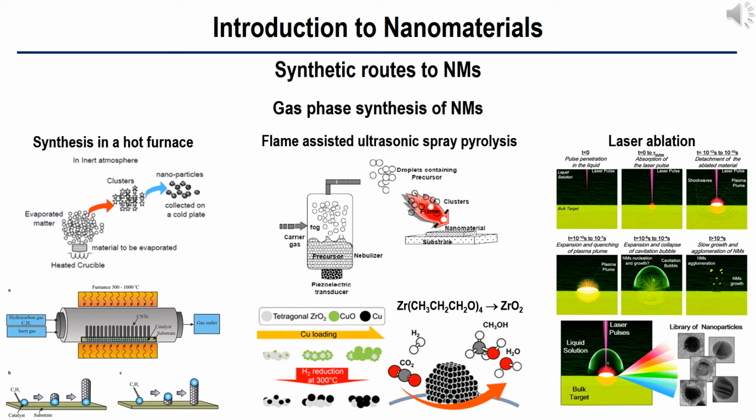In case a compound is being synthesized, these precursors react in the gas phase and form a compound with the material that is separately injected in the reaction chamber. The clusters would continue to grow if they remain in the supersaturated region. To control their size, they need to be rapidly removed from the supersaturated environment by a carrier gas.